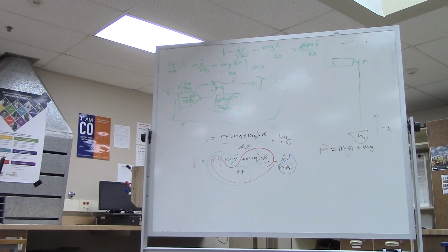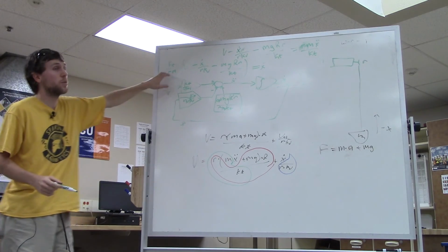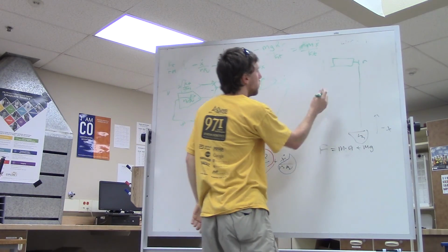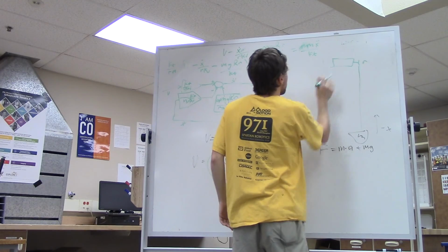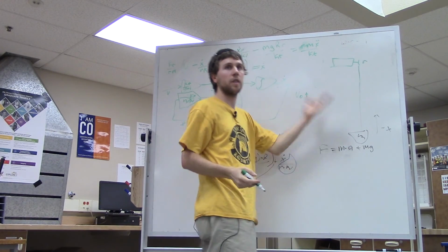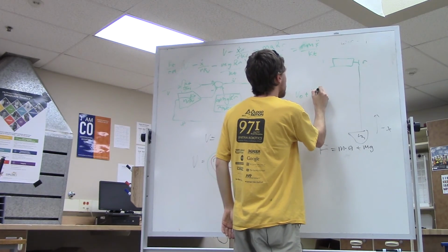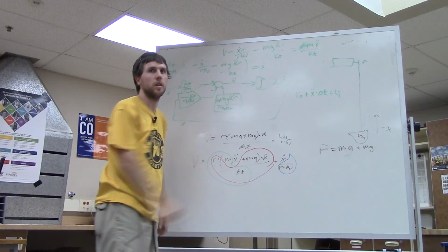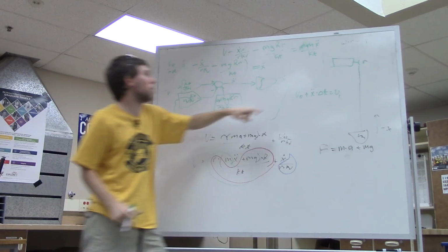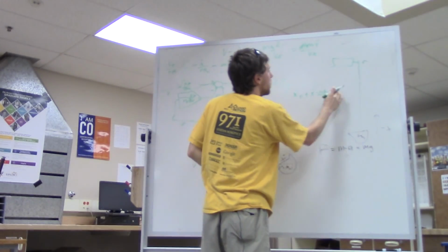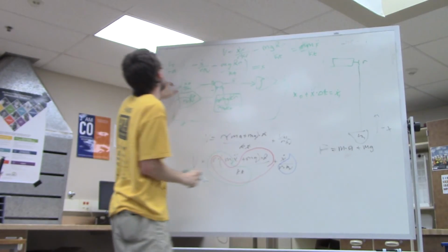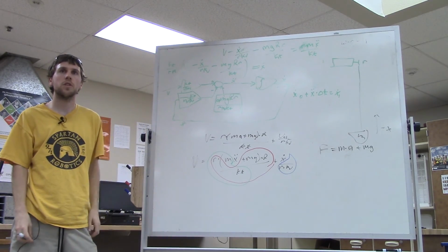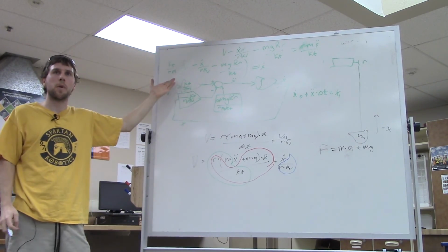Yeah. So why do you rearrange that equation to fit this one? Well, so let's say we have V0, and then we want to integrate it for one cycle. We want to take x double dot times delta t equals V1, right? But x double dot's right here, so we can just substitute this in. And we can say x dot 0 equals x dot 1. So then this says that x dot 1 is a function of x dot 0 and your voltage. So this just gives us a direct way to program up our model.